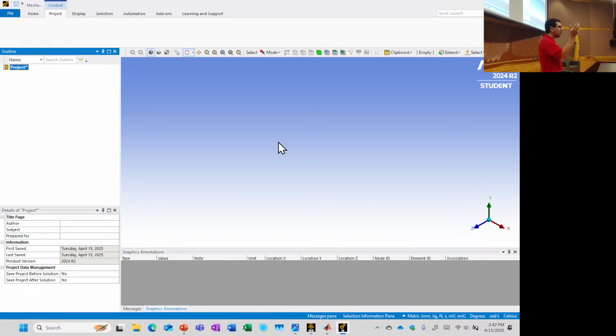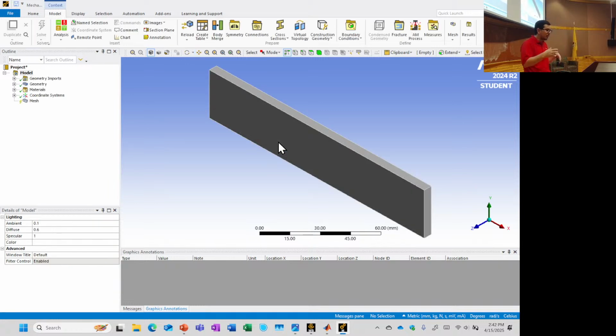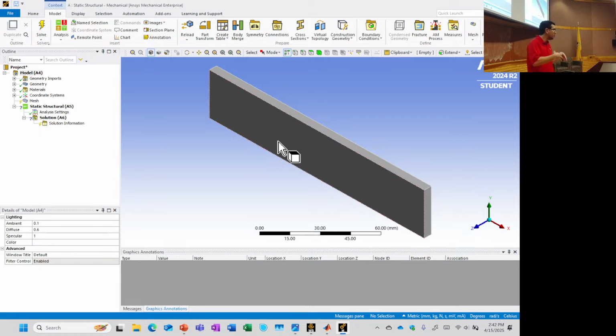You're like, well, we already got the Euler and the Johnson. Why even do the ANSYS? I just use Euler and Johnson. Well, not everything is a constant cross-sectional profile, right? We're doing a very simple case here. Nonetheless, if you have a more complicated geometry, a table or something else, you can do that and it will calculate for you where the hot spots for buckling might be.